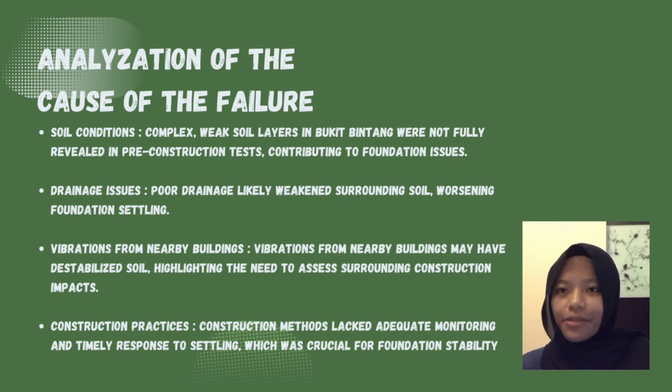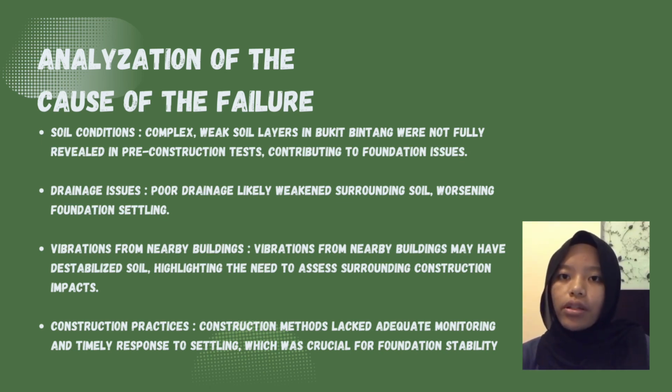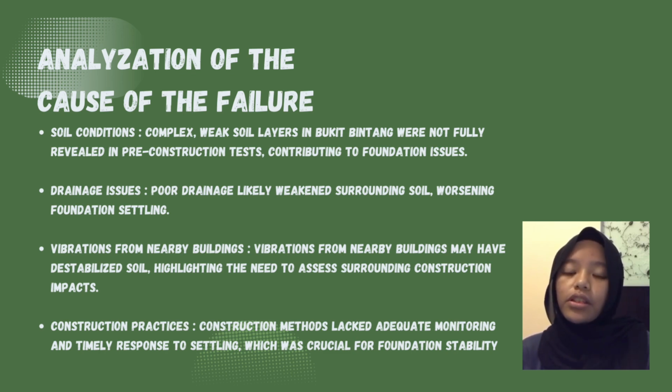Analysis of the cause of the failure. First, soil condition. The complex weak soil layer in Bukit Bintang was not fully revealed during the pre-construction soil test, which contributed to the foundation issue. Second, drainage issue. Poor drainage in the surrounding soil weakened the foundation, causing the settling problem. Third, vibration from nearby building. Vibration from the nearby building may have destabilized the soil, highlighting the need to assess surrounding construction impact.